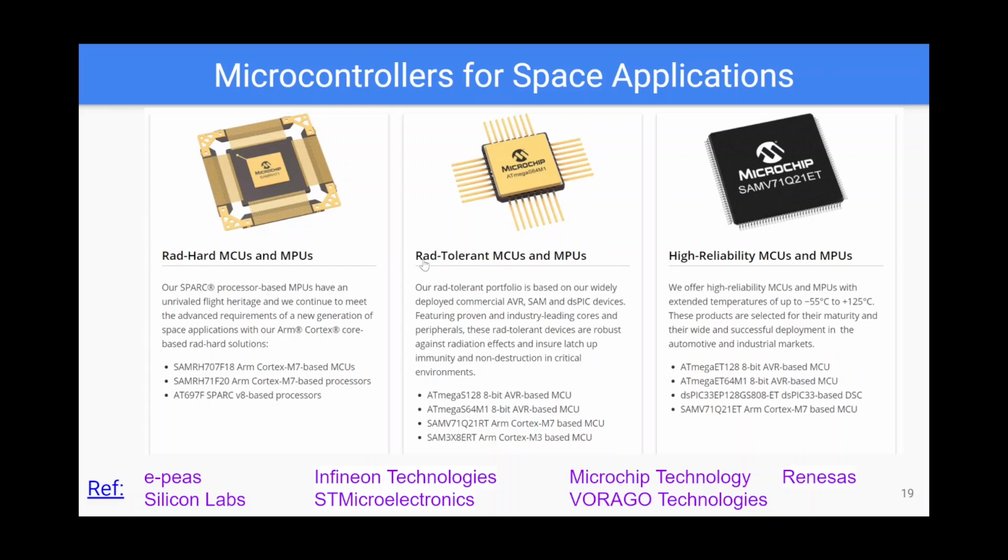It has to be rad tolerant, which means radiation tolerance is very important. Radiation hardened MCUs and MPUs, and highly reliable. The main important thing I wanted to share is that the microcontrollers or any other IC going into space has to be radiation hardened and radiation tolerant. Okay, that's the most important thing.